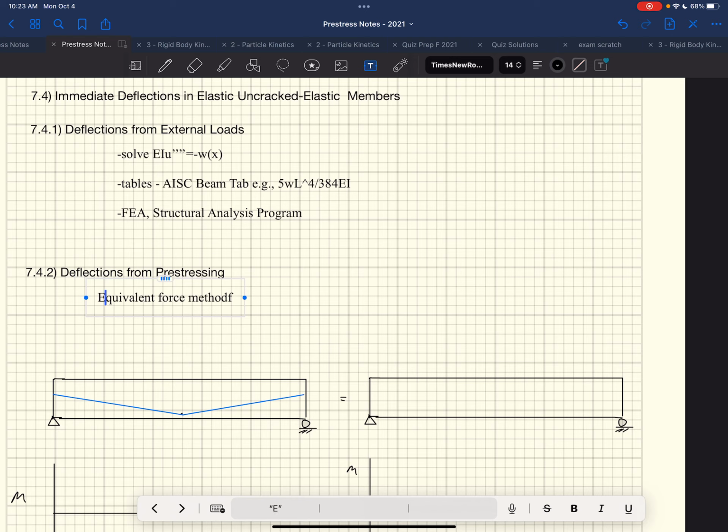Let me go here. We'll watch it play out. Yep, equivalent force method. That's right. You find the loads that give you the same effect. You find the same external loads that give you the same effect as the internal loads, and then you apply the external loads to it, and then calculate deflections or moments and stuff like that. Even though you're treating it as if...